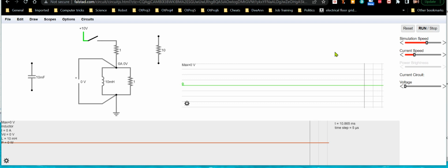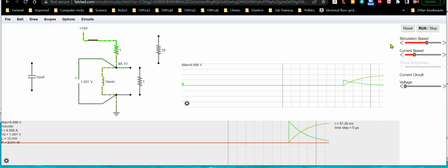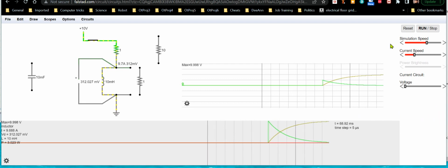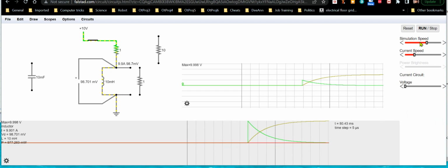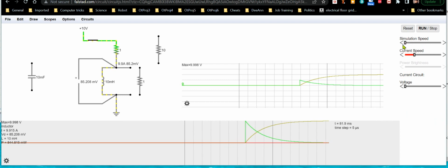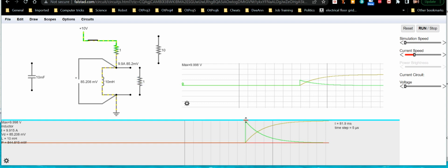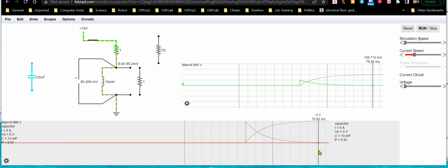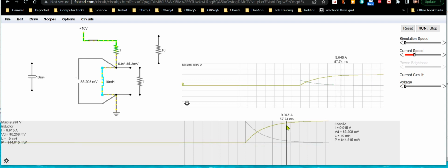Okay. Now here we have a default state. Now let me remove this resistor, and then let me charge up the inductor real quick, because this is a very important thing I left out in the theory earlier. Alright, so I popped that to 0, and I showed you what happened when we had 1 ohm charging the inductor and 1 ohm discharging it. You saw that the voltage flipped. It was like 10 volts here, and then it became negative 10 volts on the other side as the inductor current was discharging.